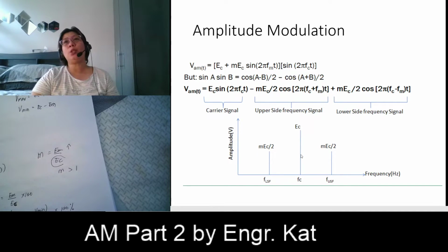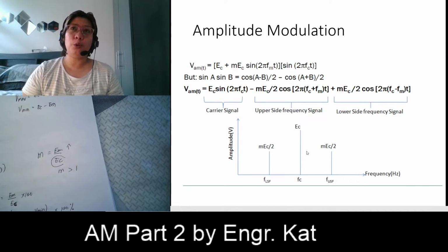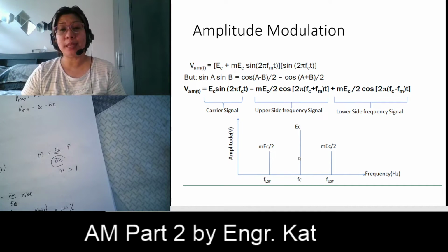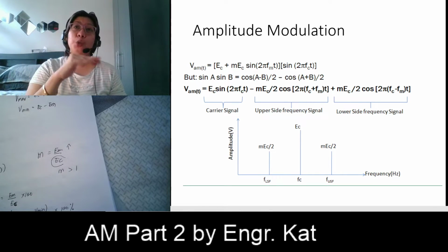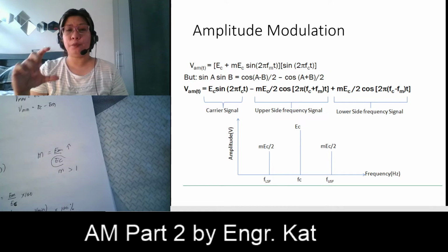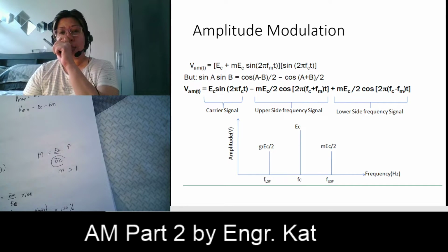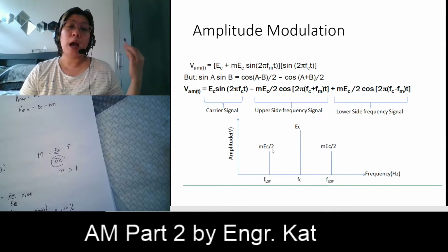So, that explains why in our previous diagram, although we don't have yet a numerical value for the sidebands, we have already drawn that your sidebands have somewhat smaller amplitude or voltage value. That is because our M is always lesser than 1, so it's a decimal point, and any value multiplied by a decimal point gives us a lower value for our numerator.